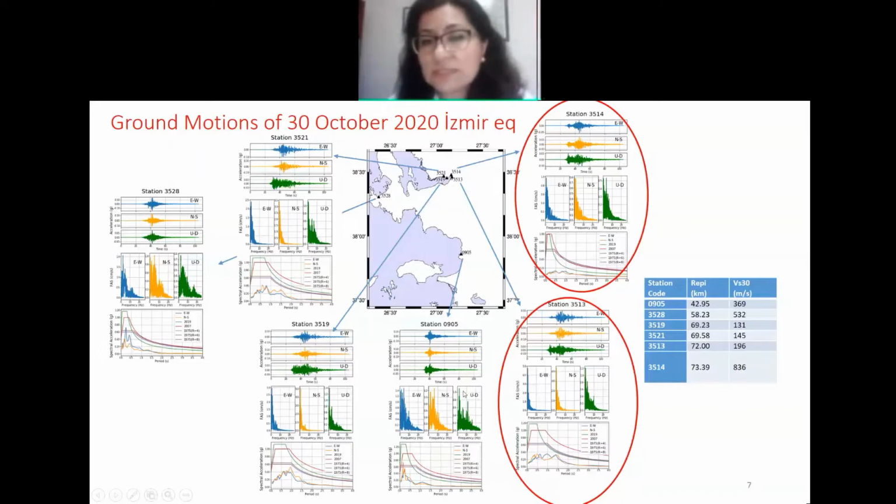In Kuşadası, I am showing you comparisons with the last earthquake code, the 2007 code and the 1975 code, because in Izmir, especially in the Bayraklı region, we considered the buildings as built according to the 1975 codes. Around this area, coming back to Kuşadası, we see some spikes over the 1975 code, but we do not have many records of significant damage here.